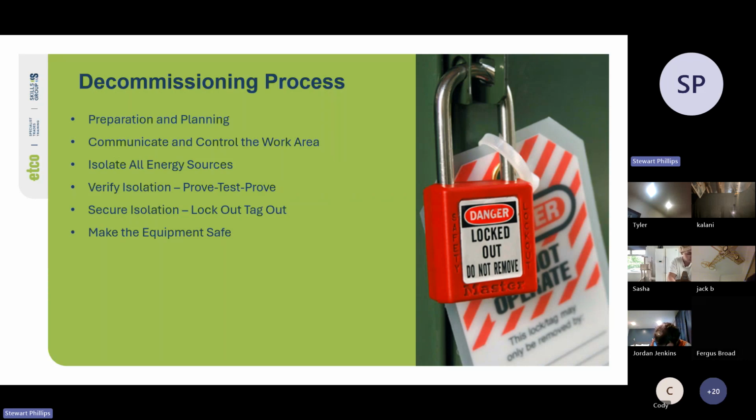And then implement mechanical safety measures. So secure parts that could move or create a hazard during maintenance. So chocks, supports, and restraints. You perform the maintenance or repairs, so you ensure all of the correct PPE and tools and maintain safety standards throughout the maintenance process.